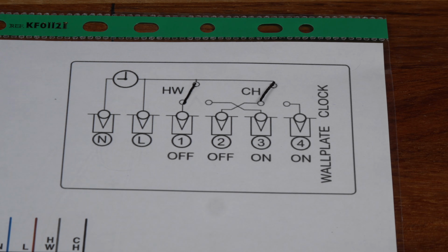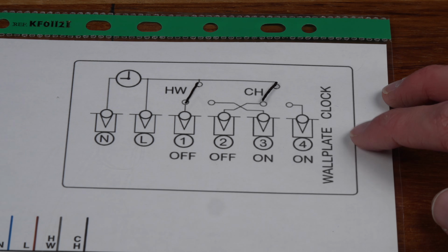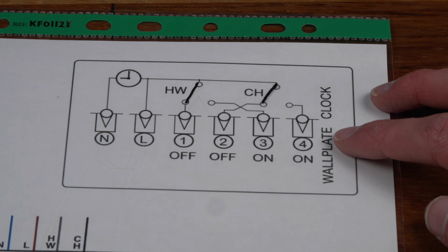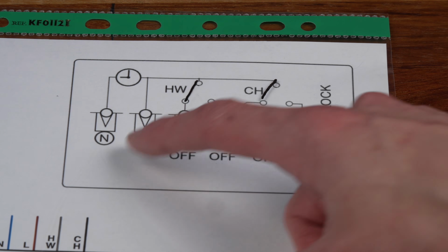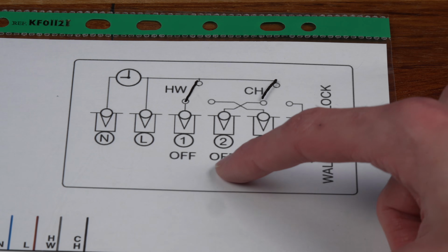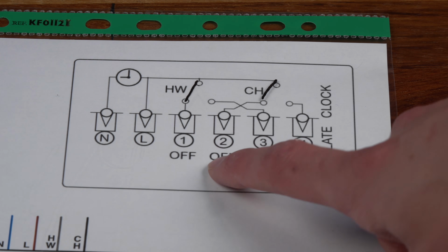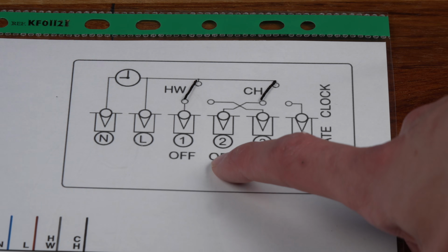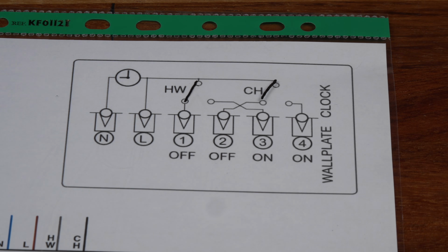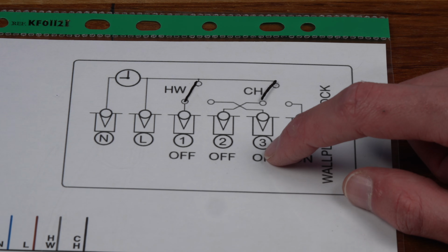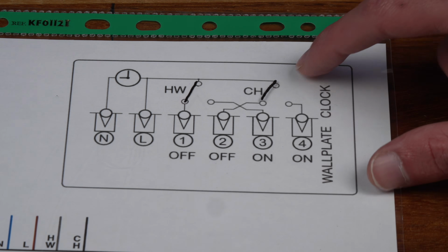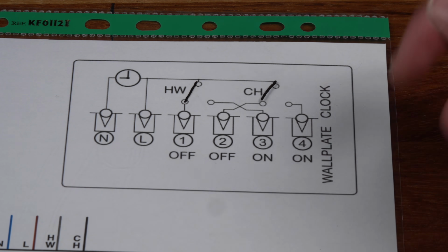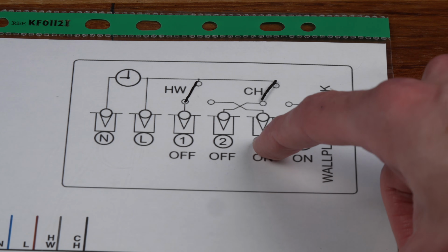As you can see, the wiring is now a bit different because this hub can control both heating and hot water. Like before, we have line and neutral terminals to power the hub, and then we have 2 sets of on and 2 sets of off terminals, 1 pair for the heating and 1 for the hot water. On this hub, terminal 3 represents the hot water being switched on, and terminal 4 represents the heating being switched on. In this current state, they're both switched off.